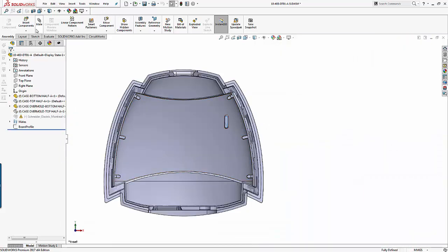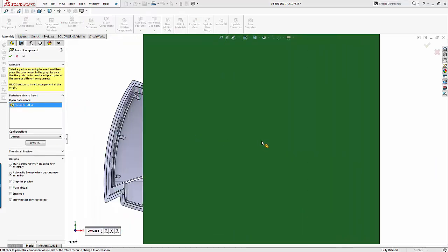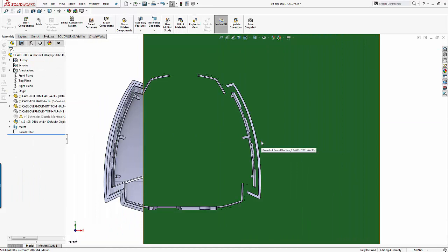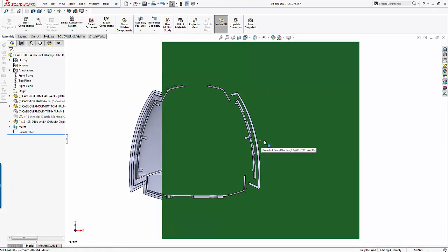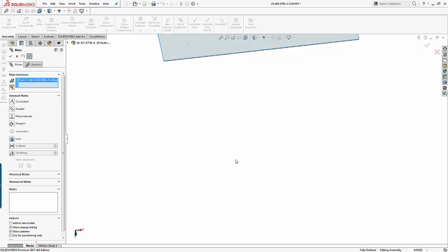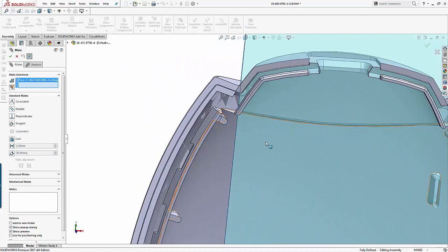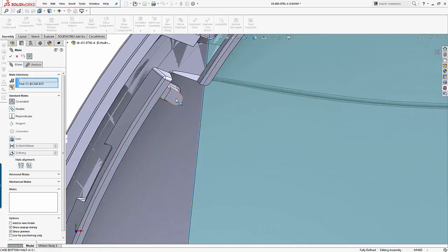So from the enclosure, we'll go ahead and go through this process. For all of you that are familiar with SOLIDWORKS mechanical design, you'll be very familiar with the steps that I'm going through right now. So I've simply read the board in. I'm going to determine which surfaces are mated together. So I know that the board needs to mate exactly to this surface here.